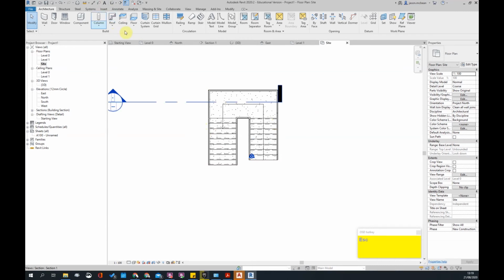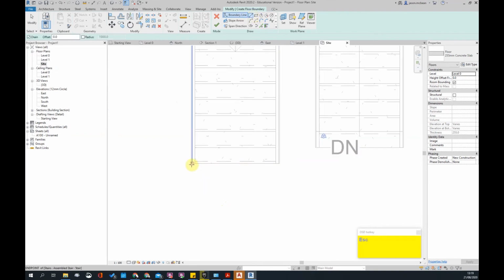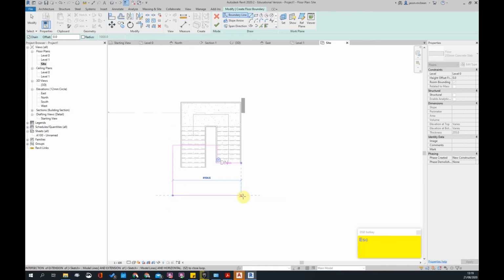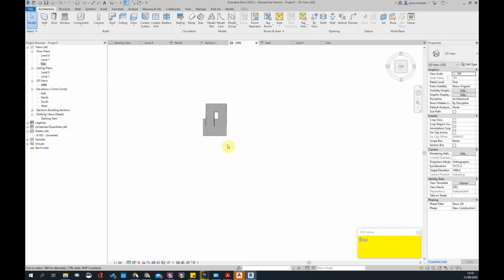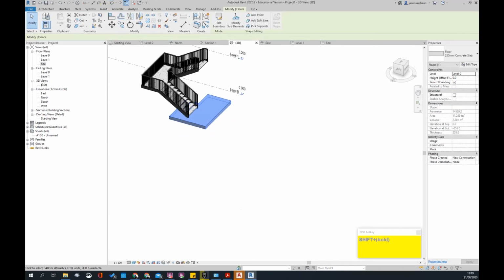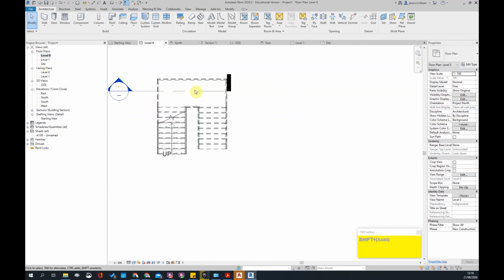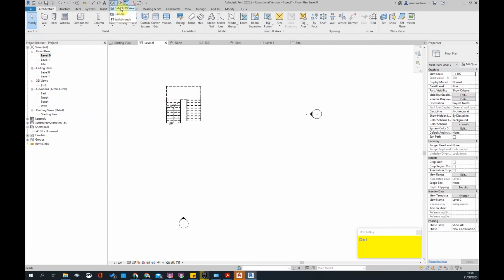Okay, cool. So what I'm going to do is go to floor and quickly draw a floor slab here. So the stair starts here, and center this floor slab did something like that. So let's go to 3D view. It can help if we draw it on the first floor. It's very easy to fix. Okay, so now if I go to level 0, and I take the section, delete the section, I'm going to create a new section.